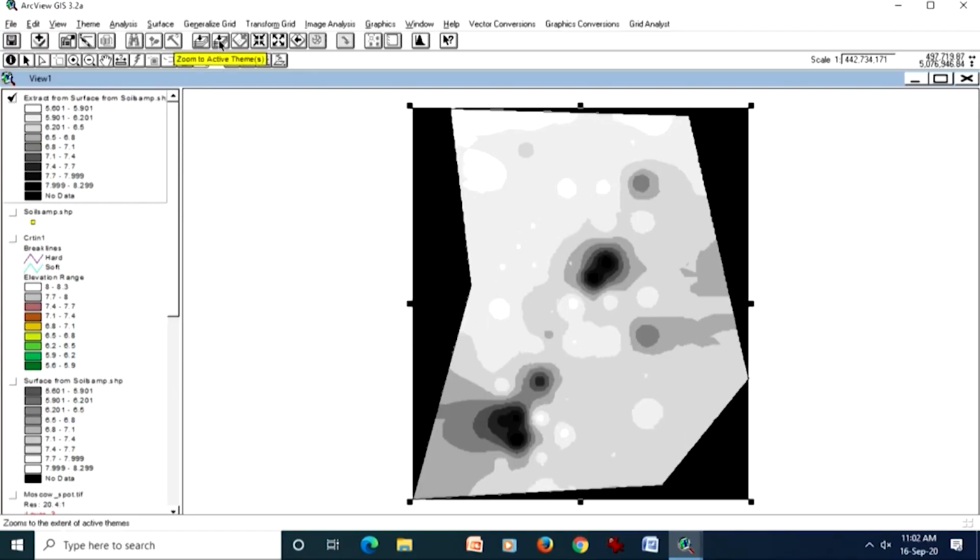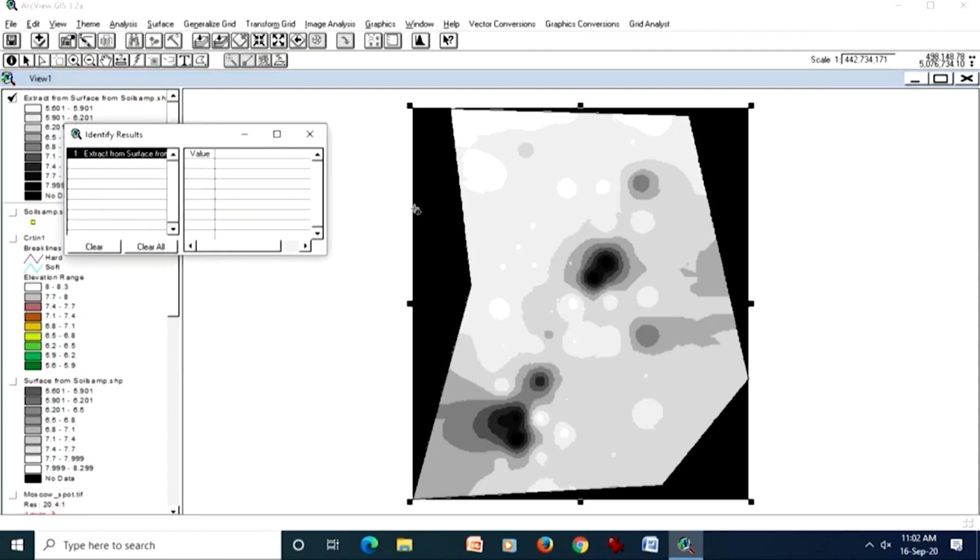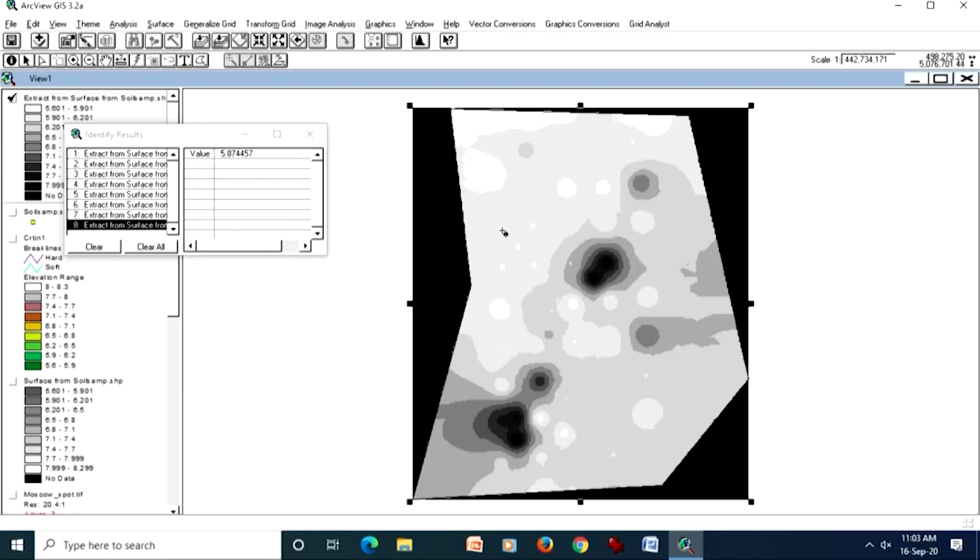And it is also satisfying that condition that the overall shape here is now rectangular. So what happens to the area which does not have any value? In modern GIS, these values are stored as no data, as you can see here. So I am not getting any value if I click on this black part. As soon as I go on the digital elevation model part, I get the values. Like here, no value, like here, no value.